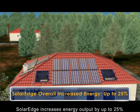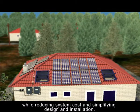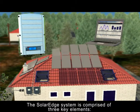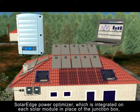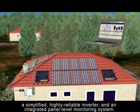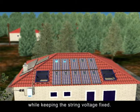SolarEdge increases energy output by up to 25% while reducing system cost and simplifying design and installation. The SolarEdge system is comprised of 3 key elements. SolarEdge Power Box, which is integrated on each solar module in place of the junction box. A simplified, highly reliable inverter, and an integrated panel-level monitoring system. The SolarEdge Power Box optimizes power harvesting by performing MPP tracking for each panel individually while keeping the string voltage fixed.